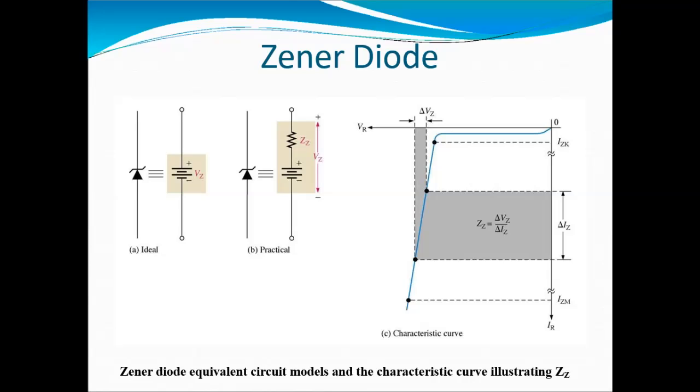Next diagram, the characteristic curve of the Zener diode. Here in this characteristic, we have current and voltage. A Zener diode always operates in reverse bias. That's why the breakdown, the avalanche effect and the Zener effect, would be seen in this Zener diode characteristic.